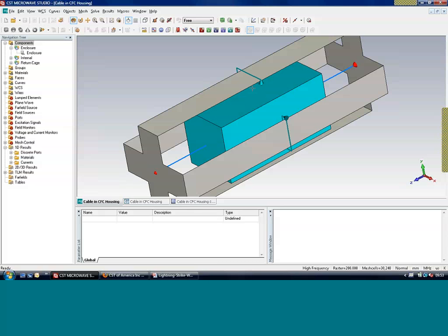On these straps here, yeah. This I've done using the new 2011 version, a beta version of 2011, and this is using a current loop in effect. It's what we call here a current monitor. So basically, what I've done here is I've just defined a path around this, and then defined that path as being where I want to get the current. It calculates the total current cutting through that loop. It's a very thin rectangular loop which we've got here.